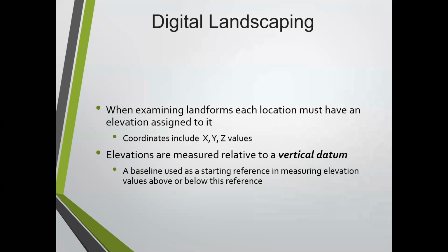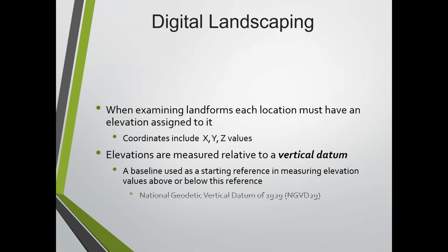Now, areas that do experience negative elevation, a lot of times they may have a local datum so that they are not dealing with negative numbers from an elevation standpoint. But for probably the majority of the lower 48 states, we're looking at just straight orthometric height, but you do have areas that go below sea level, such as New Orleans, and then there are some places like Death Valley, which is actually negative 200-something, I believe.